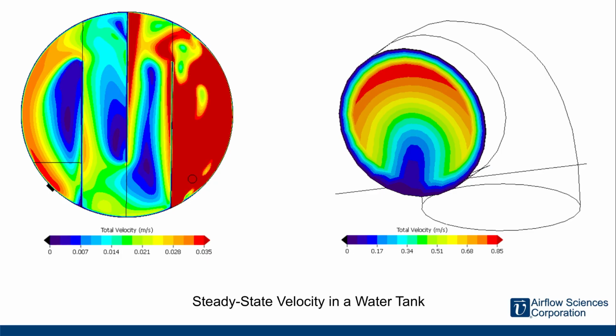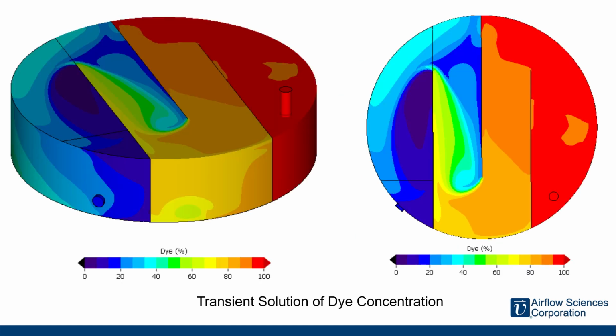The water tank analyzed for this example consists of a cylindrical tank 33 feet in diameter with an 8-foot water depth. The interior consists of 3 baffles, each 24 feet long and spaced 7 feet apart. One method to find the baffling factor by computational fluid dynamics involves modeling a dye injected into the inlet and observing the concentration throughout the tank over time.